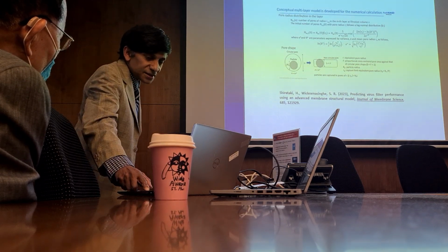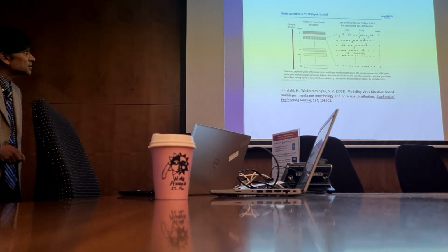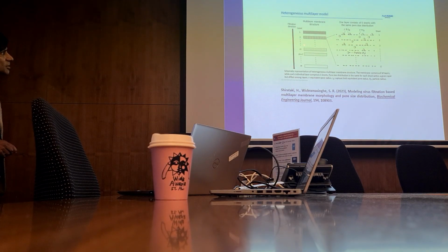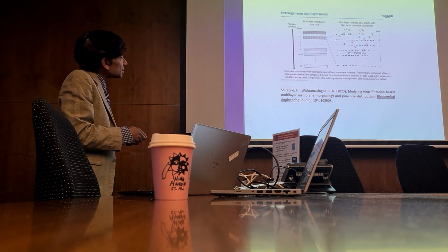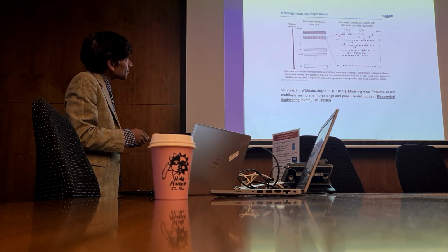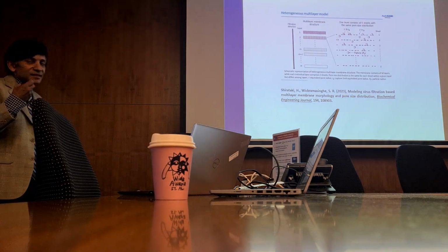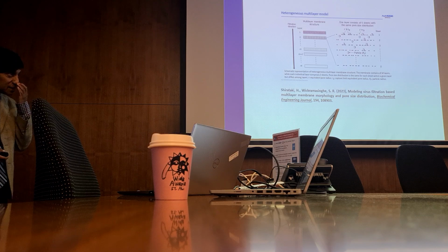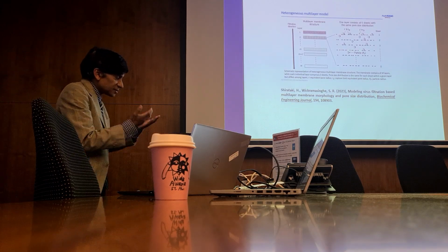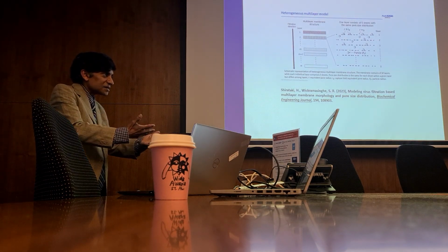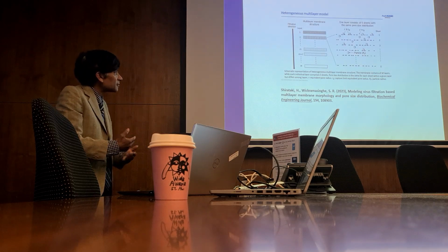And then the other thing we did in this model, these are the main features of this model, is that we break up the membrane into a number of layers like this, each of which could have its own log normal pore size distribution, or a different one, because the membrane structure is changing, right, as you go through it. But importantly, there's a gap between them, because we wanted to try and numerically account for the fact that virus particles can back migrate and then move forwards, and in this way can be trapped in lower and lower layers. So it's not like virus particles of a certain size are all trapped in one layer and then the next layer and the next. There's a possibility of going back and forwards.